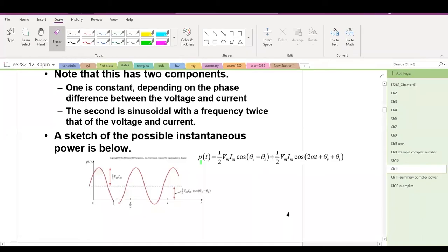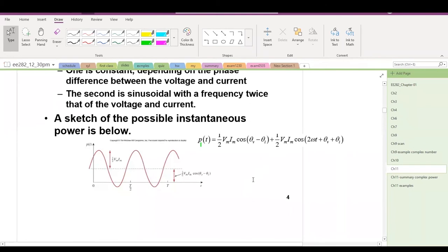We can see that at some times the instantaneous power can go to negative values, and this is because the impedance contains inductors or capacitors. Those devices can store power or release power. We know for DC circuits and for pure resistance networks, the power on the resistor is always positive, it cannot go negative. But in an AC circuit, that's a different scenario. Because the instantaneous power is changing with time, next let's introduce the average power.